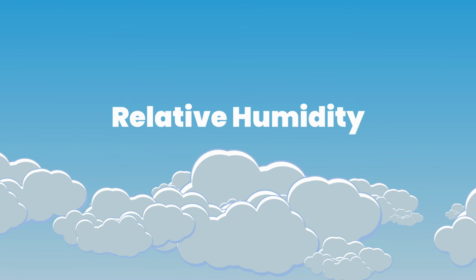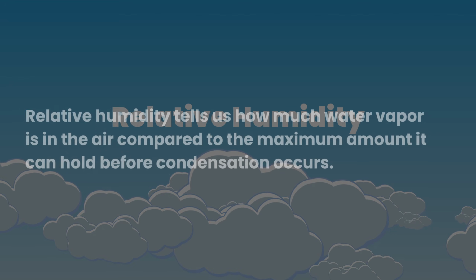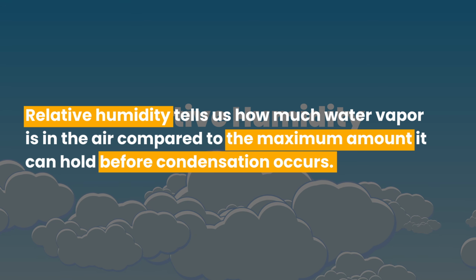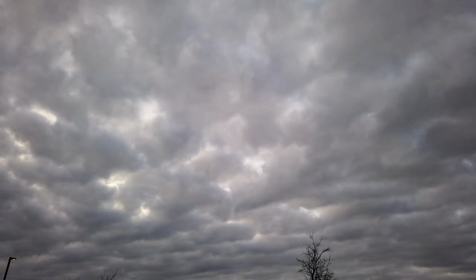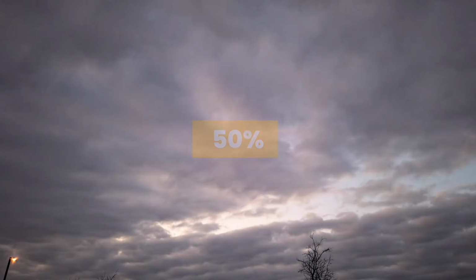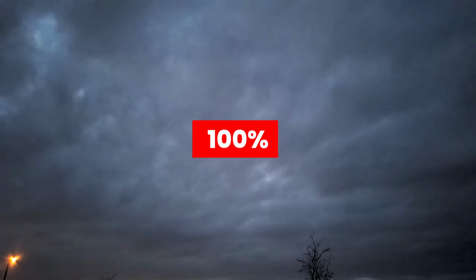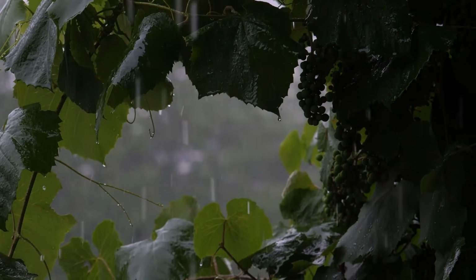Now let's talk about relative humidity and how it shows up on the psychrometric chart. Relative humidity is basically a measure of how much water vapor is in the air compared to the maximum it can hold before condensation happens. For example, if the relative humidity is 50%, that means the air is holding half of the water vapor it's capable of holding at that temperature. As more water vapor is added, the relative humidity rises. When the air reaches 100% relative humidity, it can no longer hold any more moisture, and condensation begins.